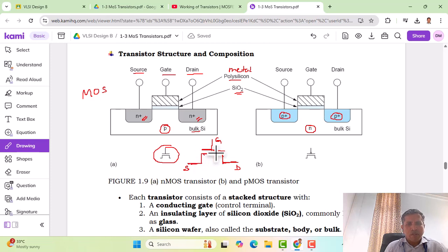And here we have the channel formation region, and the top layer is nothing but the metal, and there's a space between the metal and the semiconductor. That space indicates it is the silicon dioxide SiO2 region, and we attach the gate terminal to the metal.